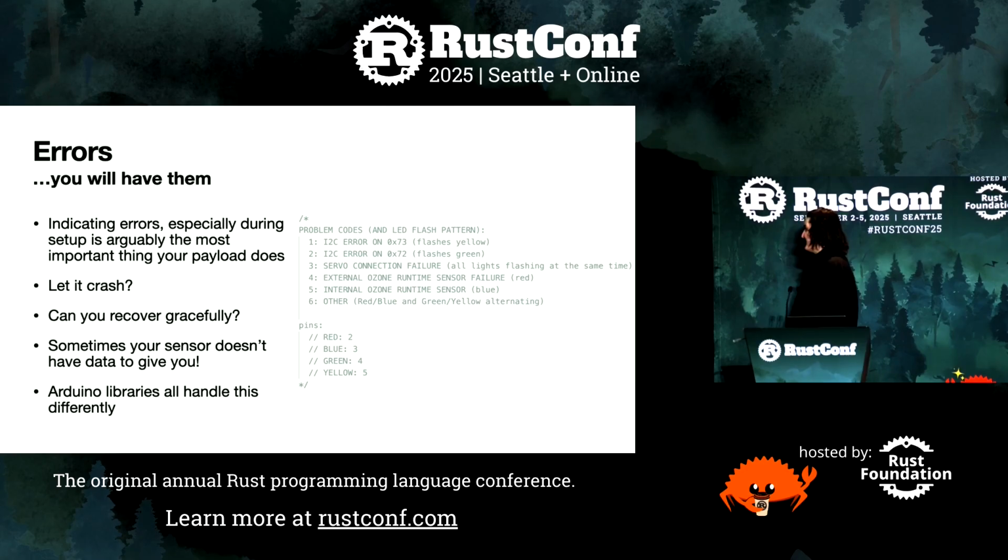And you have errors. Definitely you have errors. I've never seen a project that just works, especially in the balloon stuff. We had some strange issues with having the proper reference voltage for our analog to digital converter, if anyone's familiar with some Arduino stuff, that getting the supply voltage or just the wrong wiring can be an issue.